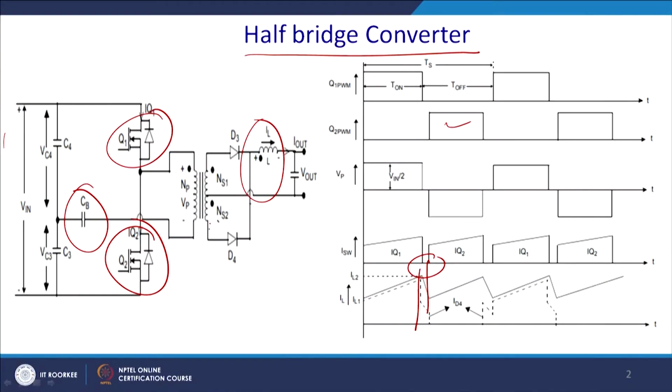So, what essentially do you get here, what is the advantage over the other topologies? We have discussed flyback, thereafter the forward, thereafter push pull, then it is this. One of the advantages is that its power handling capability can be very high, because there is no concept of resetting flux separately; you are resetting flux in every cycle, and thus we need not have a resetting winding, and stresses across the switch will also be low.